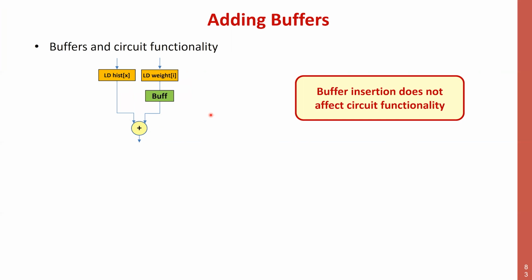This is not the case here, though, because in this kind of data flow circuits, what happens is that when one token does not arrive to the plus because it's stopped in this register, the adder has this internal synchronizer and pushes back the other token and keeps it waiting until both are ready.